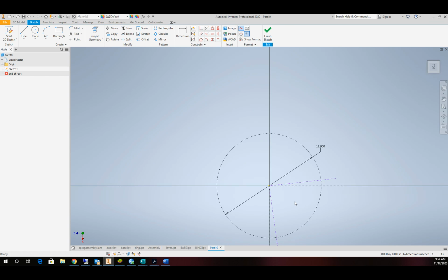This is going to establish some distance so we can use some points along here. I'm going to place an angular dimension here. We're just going to make that 6 degrees, and same over here, and we'll match that to that.